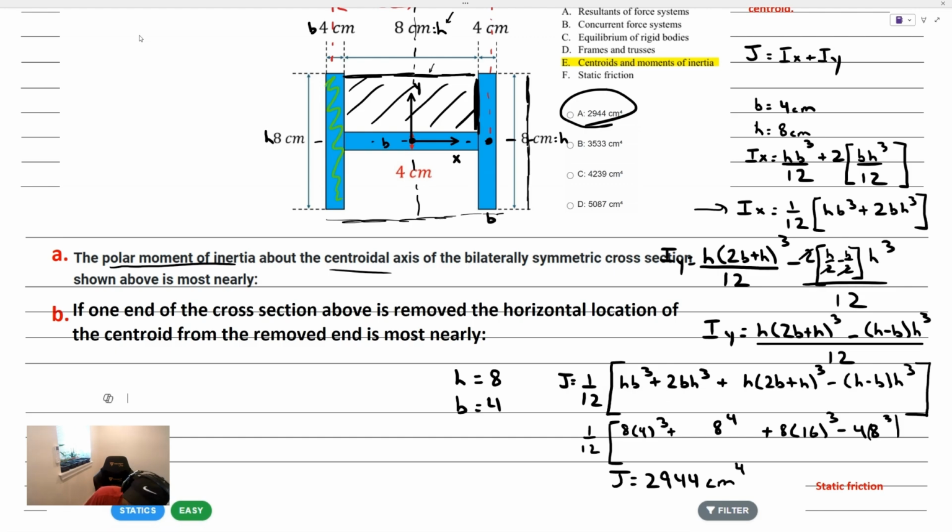So that's pretty much this shape down here. Let me move over a little bit. We have a kind of T shape. And why I included this problem is to point out something super important about the idea of a centroid. Now, centroid is just the first moment of area. We have side length of 8, 4 here, and then this is 4, and this is 8.